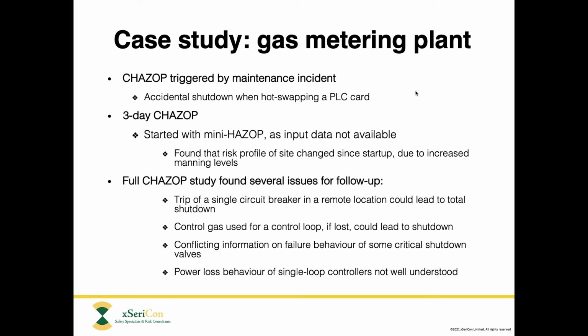And then we would identify the consequence by looking at all of those fail low cases that we identified in the HAZOP study. And that will tell us what is the reasonable worst case consequence. And from that should actually tell us whether a software criticality analysis is appropriate. Because if that's a very serious consequence, at least not well controlled by safeguards, then we might say, well, this software is really mission critical, and we need to be looking at it in very fine detail to confirm that the validation of this software was highly robust.